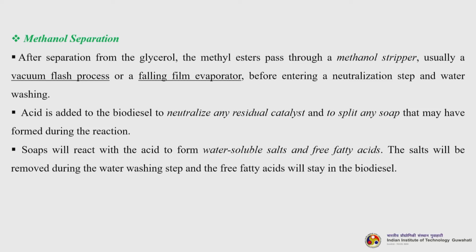Acid is added to the biodiesel to neutralize any residual catalyst and to split any soap that may have formed during the reaction. Soaps will react with the acid to form water soluble salts and free fatty acids. The salts will be removed during the water washing step and the free fatty acids will stay in the biodiesel.